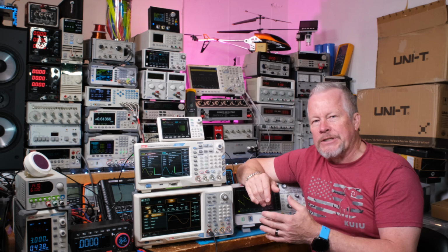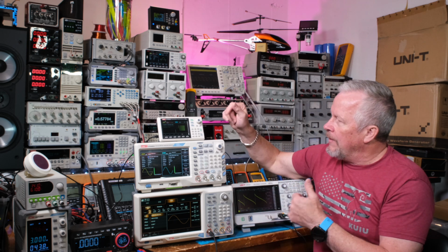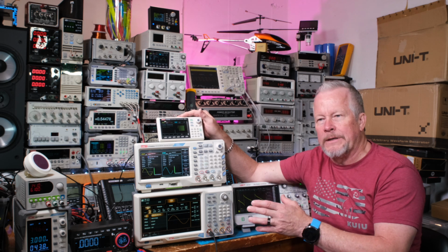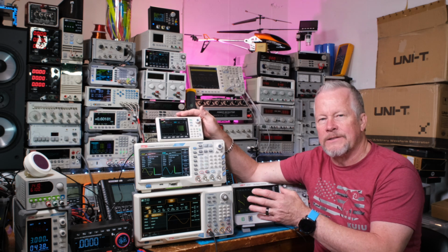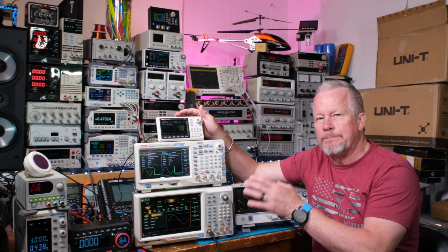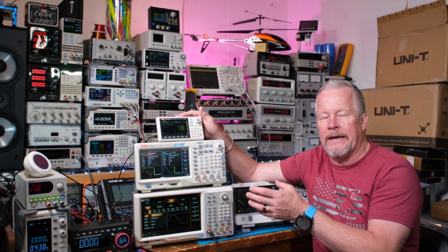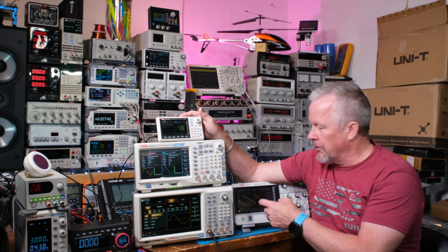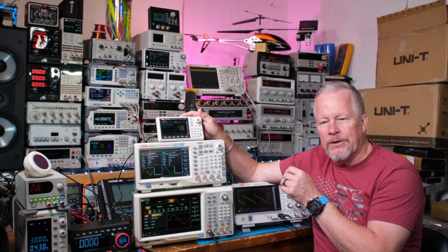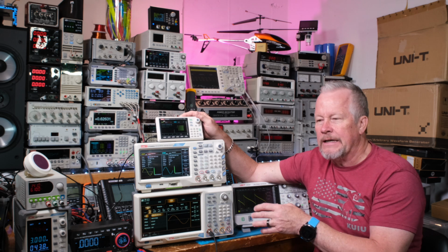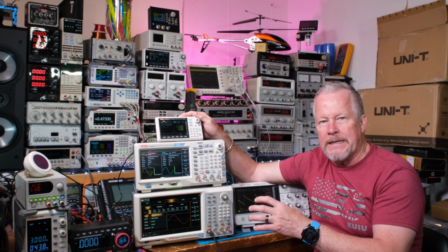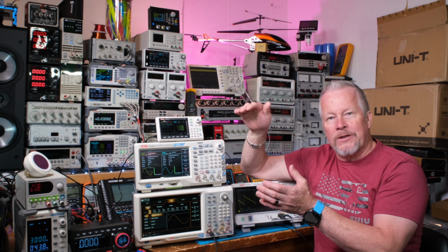That takes me to the voltage thing real quick. I believe all of these guys can go up to 10 volts in high res, or 20 volts. So I think it's 20 volts peak to peak in high impedance. I'm just reading off the high impedance of the scope, but if you're going into an op amp, some high impedance circuit. Now, if you're going into some low impedance, 50 ohm, 75 ohm, then the voltage drops in half. So it's 20 volts at the lower frequencies.